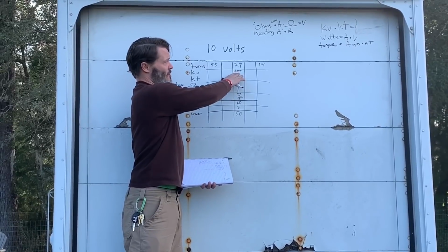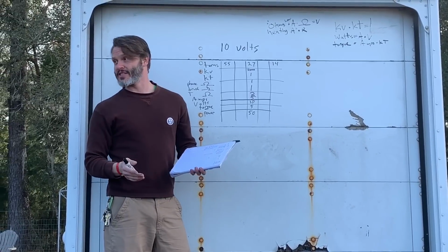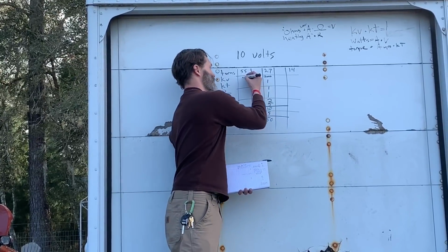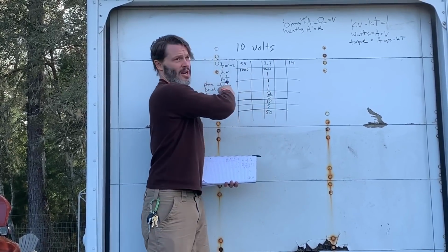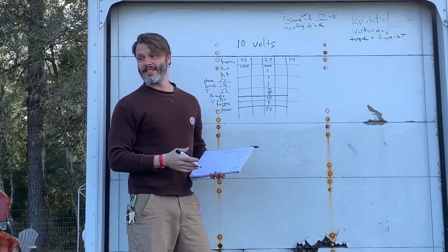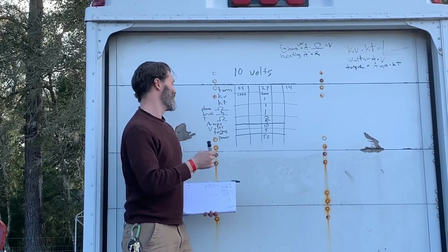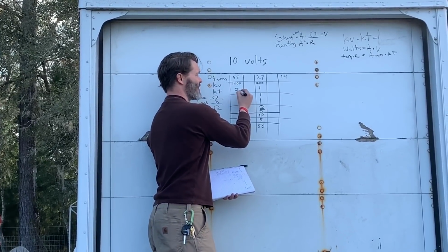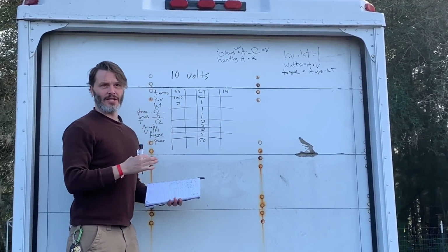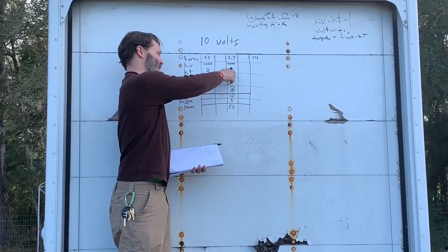Now, we're going to start back up here again. 2,000 KV for a 27-turn motor. Half speed of that is going to be 1,000 KV. And we know from experience about a 55-turn motor is 1,000 KV. Now, when you halve your motor speed, your torque constant doubles. So now for our phase amps, we get twice the torque for the same amount of amps. However, you'll see it's not exactly straightforward. So our KT is now 2 units. And we can go back to our motor constant formula, and you see it's a linear relationship on there. And that is why the KV and the KT, the voltage constant and the torque constant, are easy to figure out. So we can do numbers like this.